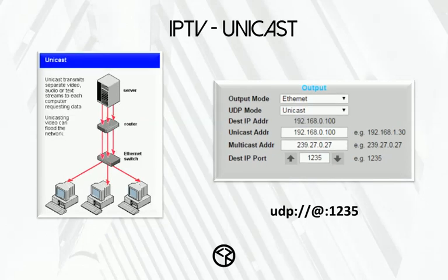The settings that you made set up a whole communication going on within the switch to make streaming happen between encoders and servers and players, decoders, and PCs that might want to watch the streams. The old way things were done, unicast, was very simple. As shown here, you would have a unicast address, which is an actual address of some PC on the network, and that has to be set up in the encoder.